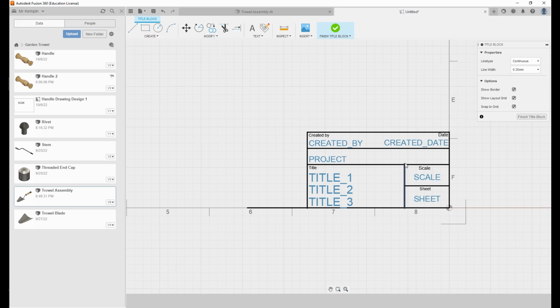Okay. Oh, I don't like that little bump there. So if I extend that drawing up a little bit, I can go to my trim tool, trim that bit off, press enter, and that's done. Oh, I need to trim that bit there off, don't I? There we go. Trim off the tiny little bits if you're careful. Press enter to finish. For the first couple of times I've done this, I did press escape to finish, and that was a bad idea. And now I've got my drawing block, my title block, sorry.